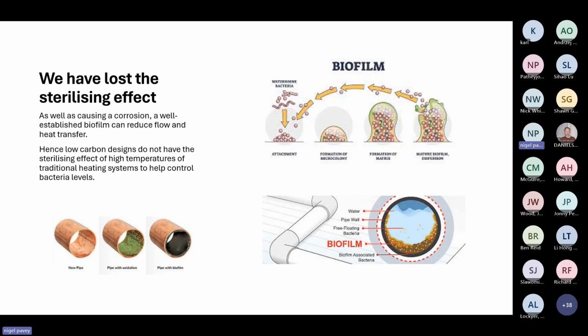So you'll end up having to cleanse the system, putting chemicals in to get rid of this biofilm to control the water quality. And once you get into that situation, it's extremely difficult to get those systems back to normal operation. Once you get rid of the biofilm, well, how did it get there? Was it because the water velocities were too low? Did I have control valves closing many items of the system off so the chemicals couldn't get through? Very simple questions to answer.